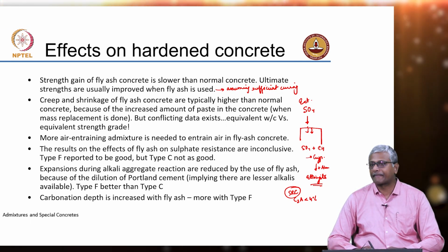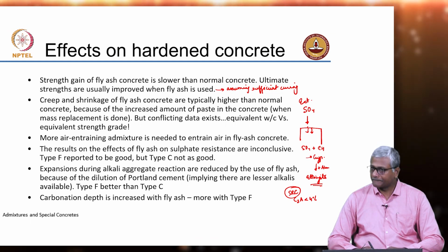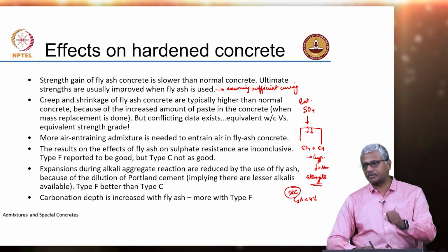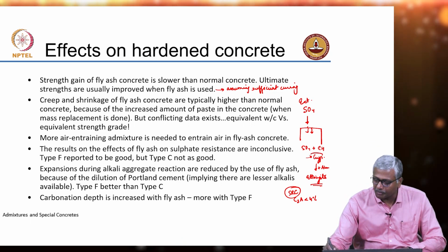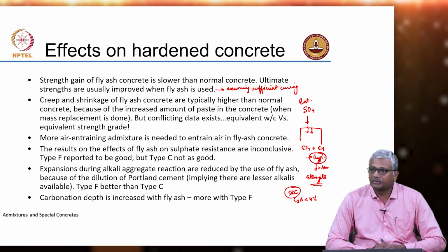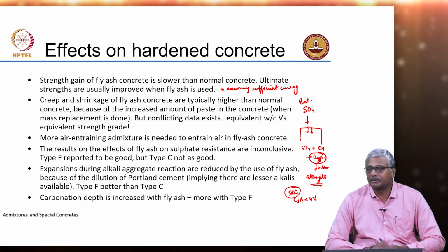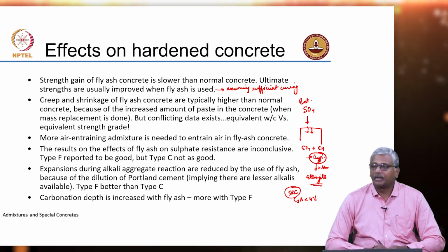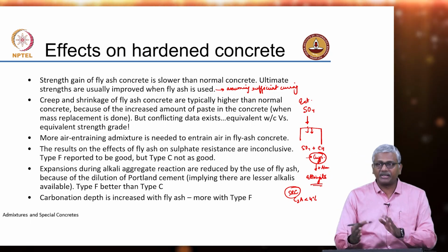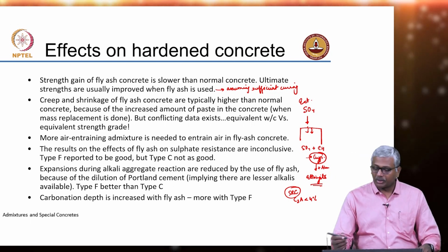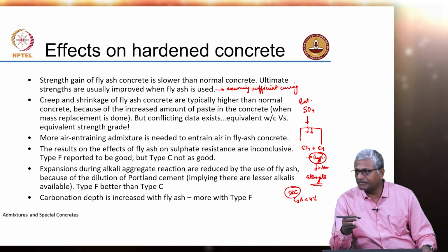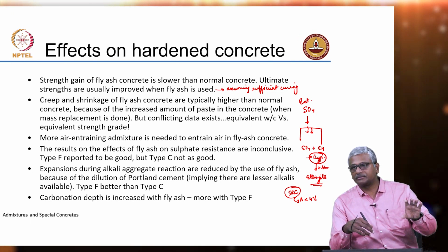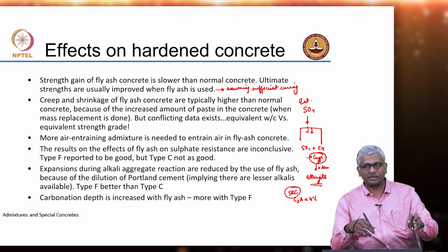Sir, if we add fly ash, then the silica in fly ash will react with calcium hydroxide. Silica will react with calcium hydroxide because of pozzolanic reaction, cutting down the amount of calcium hydroxide available. So, that means this gypsum formation is going to come down, it is going to reduce, right. What else will happen? Less additional ettringite may be formed, but if you think about the initial phase, you are diluting your cement, you have less cement available now, more fly ash comes into the system. So, overall C3A loading of your concrete, of your cementing material, also comes down, right.